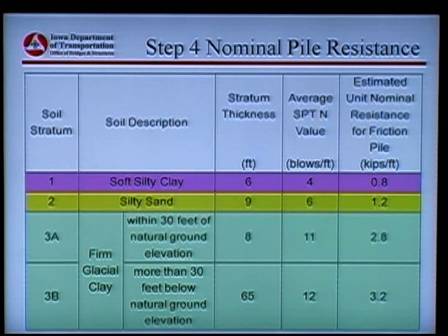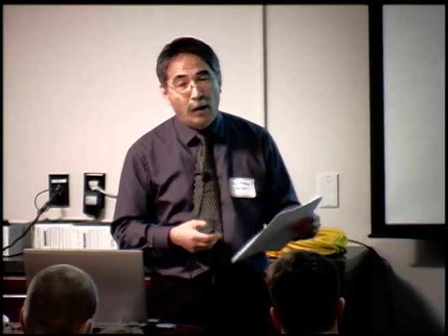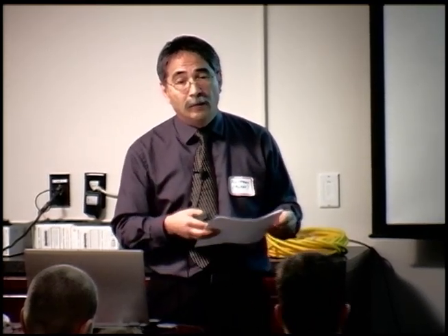Then down to the final depth down here, then 65 foot deeper, then what we're going to have is the 23, which got us down to the top of that, plus the 65, brought us down to 88 foot depth. And we're going to add to it the 65 feet times the 3.2 gives us 208, and 38 from before plus 208 gives us 246. All this is just to generate a bunch of points to generate an XY plot. What is the resistance gain versus depth?